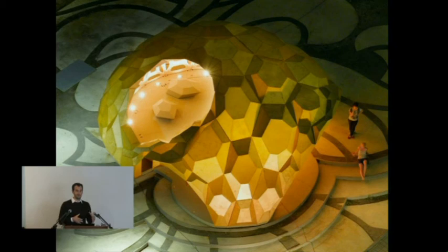So as the structural performance here really results from each element's highly specific morphological response to the flow of forces, the entire pavilion with a diameter of more than 12 meters could actually be built using extremely thin plates. All the plates, without any exception, have a thickness of only 6.5 millimeters. So that's that thick, resulting in a very lightweight and materially efficient structure that manages to enclose 200 cubic meters of space with just 2 cubic meters of wood. So it's a kind of 1 to 100 ratio.